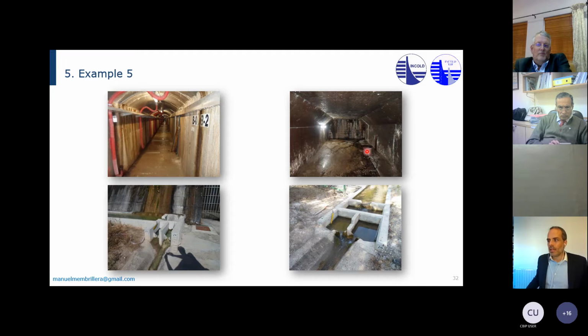So make sure the river diversion clogs have proper lighting. This lighting was installed so that we could inspect this tunnel and get to the clog and make sure that you can monitor this both visually, and if you have some piezometers there, well, even better.